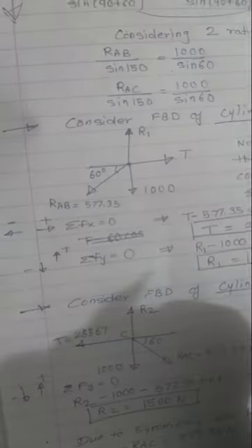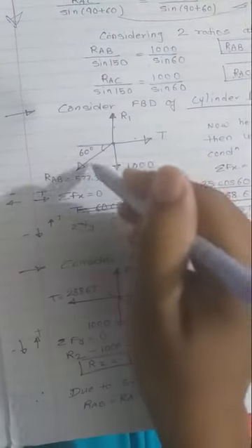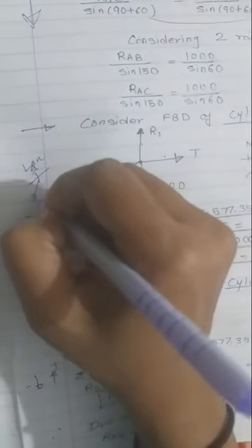Now this figure is over here. Now here there are 1, 2, 3, 4 forces. So you might think that if I know the value of this, you can apply Lami's theorem like this way, because only 3 are unknown. It is not the case. You can apply Lami's theorem only when there are exactly 3 forces. So remember that.